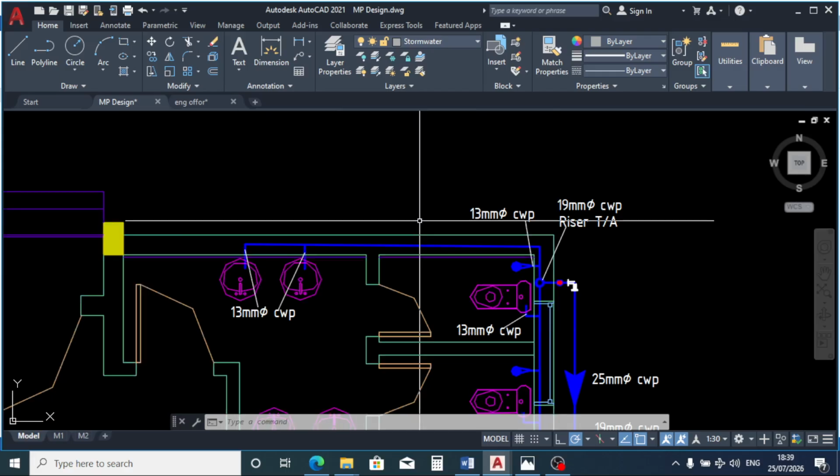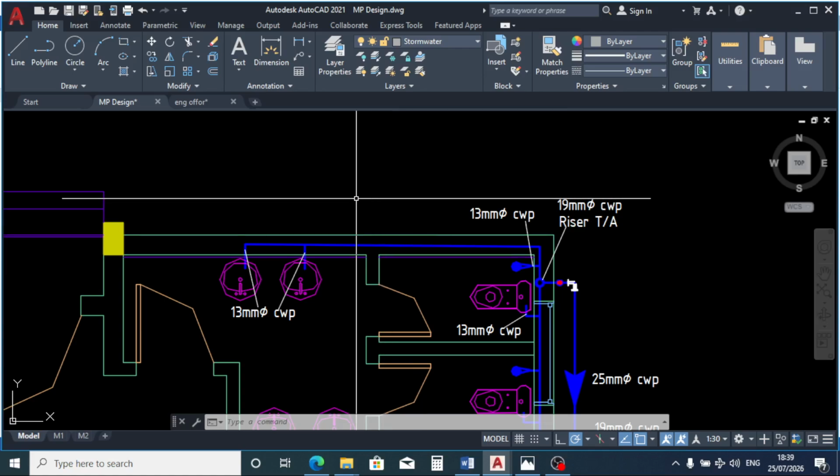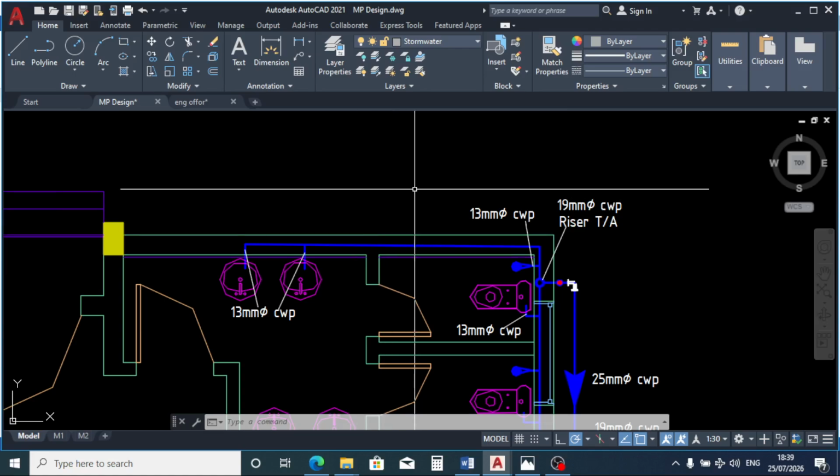Why? Because galvanized iron pipes are susceptible to corrosion and rust. If you use them over time, the zinc coating will wear off, and there will be rust in the pipe. Your water will be carrying rust in it. Water that is supposed to be clean will now be tasting of rust. The water color will even change, and there will be heavy metal leaching in the water.